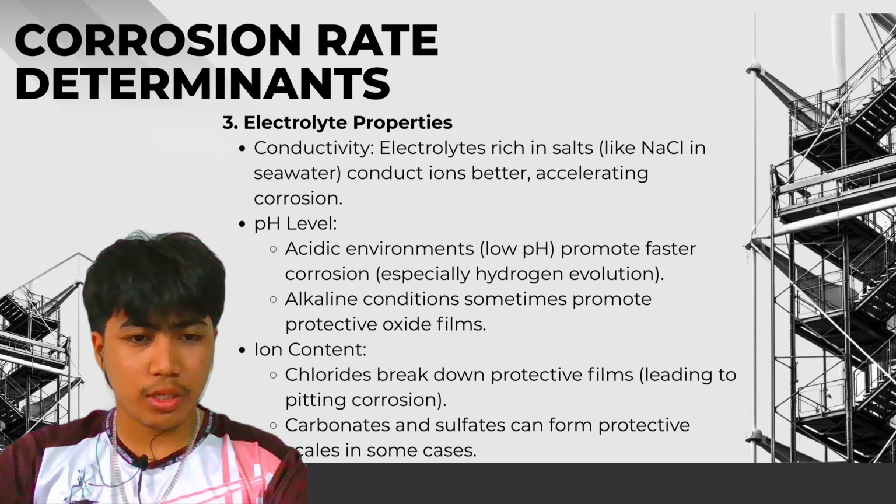Alkaline conditions sometimes promote protective oxide films. Ion content: chlorides break down protective films, leading to pitting corrosion. Carbonates and sulfates can form protective scales in some cases.